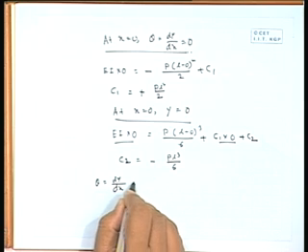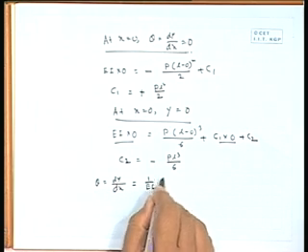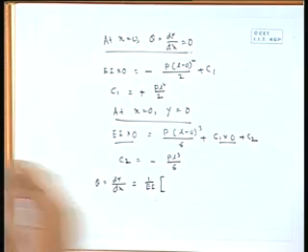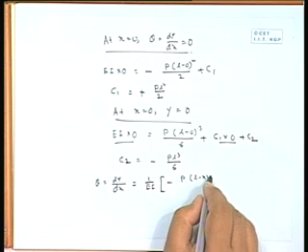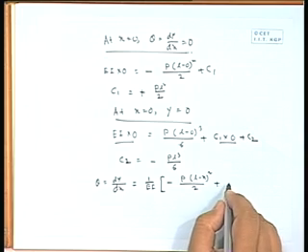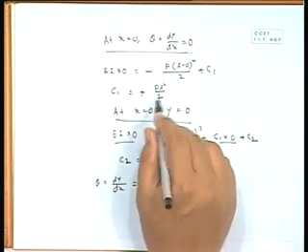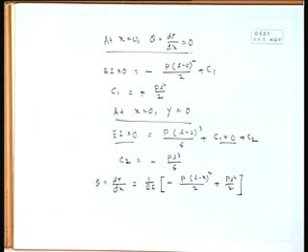If we write the expression of slope, it will be theta equal to dy by dx, that will be equal to 1 by EI, minus P (L minus x) square divided by 2, plus C1, which we have just determined, it is P L square divided by 2, right.